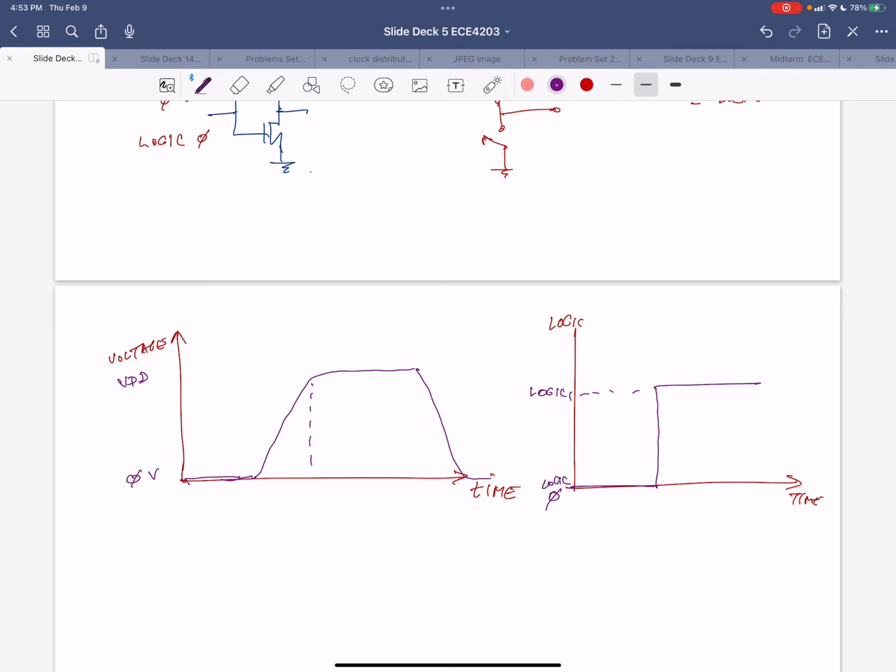And it doesn't tell us how these points, which are fairly important places, are defined, what's legitimate. Because in logical math space, you only have 0 and 1 defined. So, okay, that's a 0, that's a 1. But in a voltage space, this VDD we've called a 1, and we've called the 0 volt a 0, but is 0.9 volts also a 1?